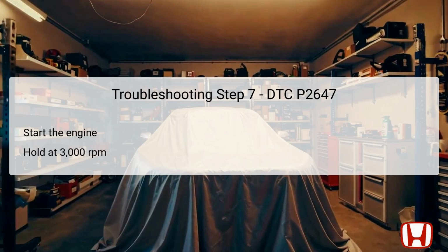The radiator fan will typically engage during this time, indicating the engine's thermal management system is functioning as expected. After maintaining the engine speed for a duration of 2 minutes, the technician should allow the engine to idle before proceeding to the next testing step, ensuring all conditions are met for accurate oil pressure readings.